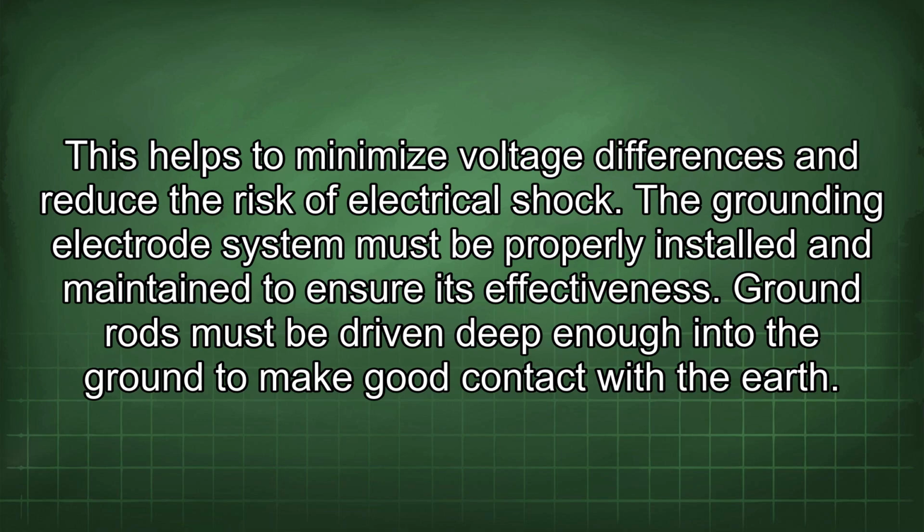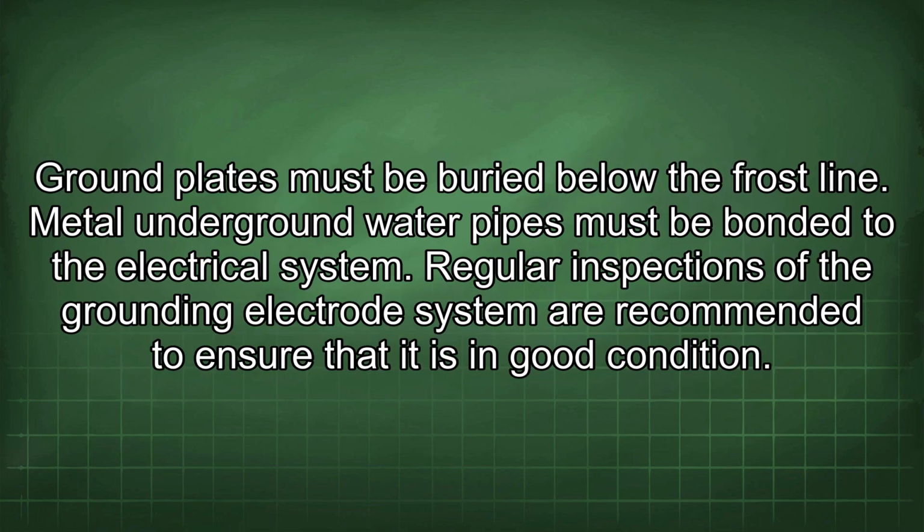The grounding electrode system must be properly installed and maintained to ensure its effectiveness. Ground rods must be driven deep enough into the ground to make good contact with the earth. Ground plates must be buried below the frost line.